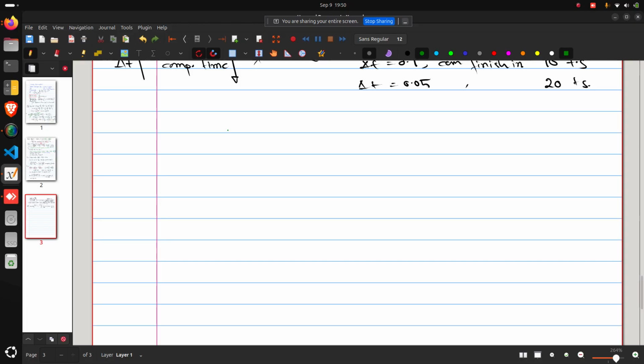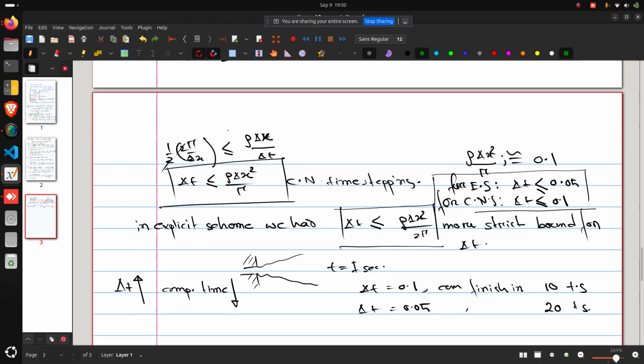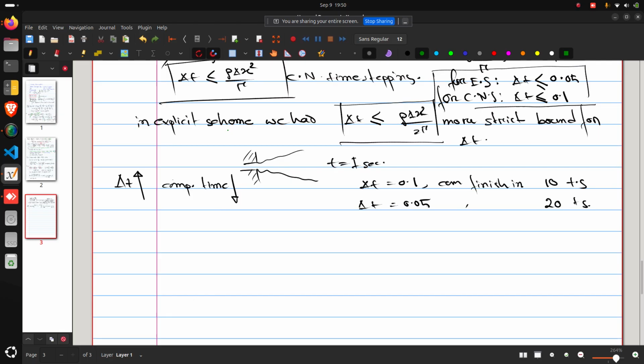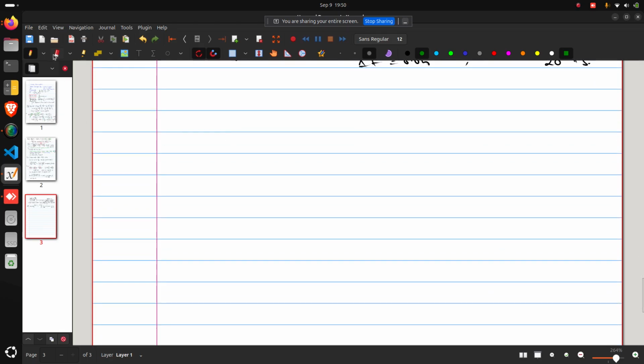And also another important aspect of the different time stepping schemes is this. If you remember, for the linear interpolation that we have done, for example, for the gradient operator d by dx at some face, say, the face east, it was nothing but phi east minus phi p divided by delta x, right?